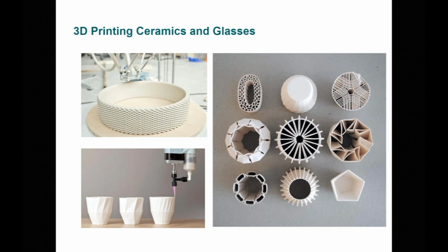So for example, in a viscous solution printing method, you can 3D print, let's say, this clay composition or any other type of composition with the resolution being dependent on the type of printing device you have. Once you form these shapes, they're not actually useful yet as a ceramic. You have to take them and you have to cure them. That is, you have to use heat treatment like any other ceramic material in order to get their refractory, insulating, abrasive property, and of course, as shown in very interesting shapes.